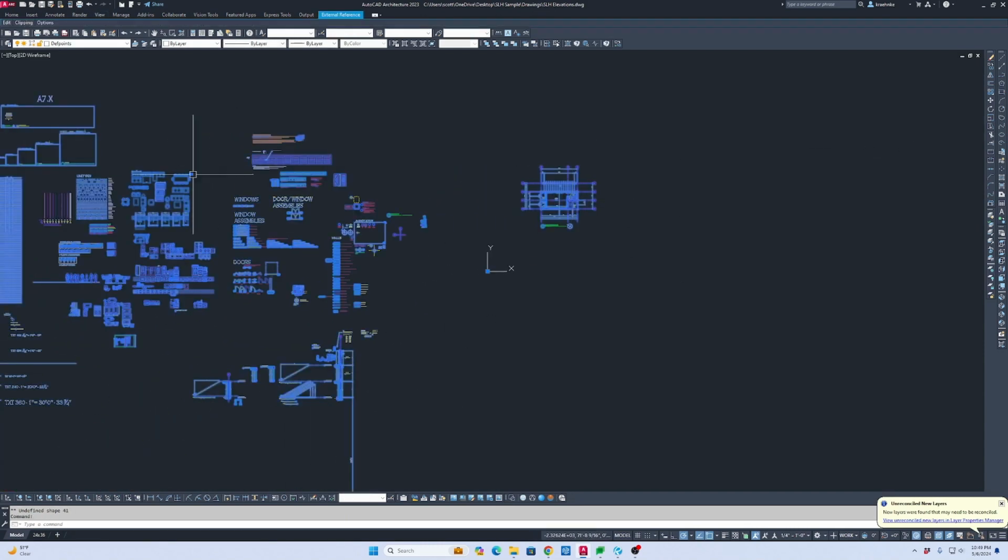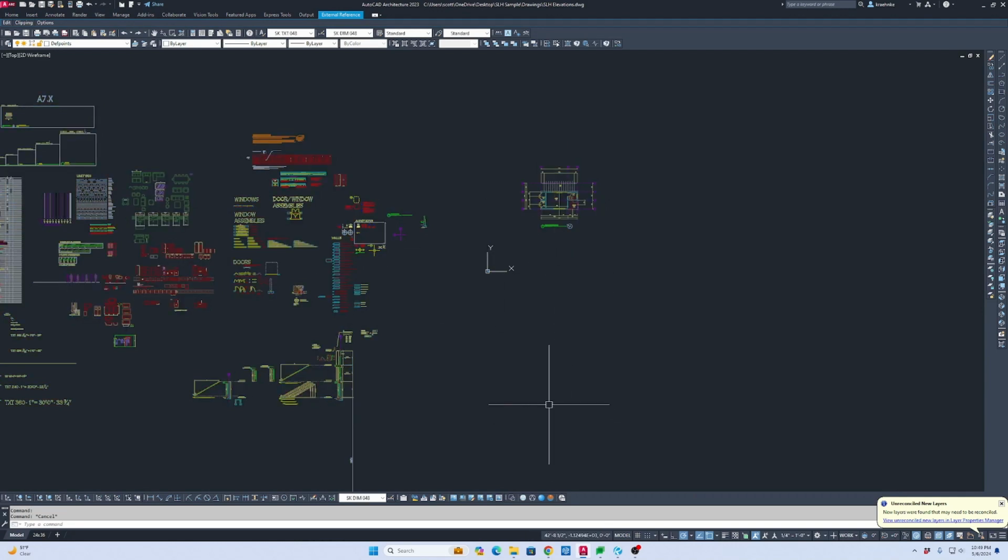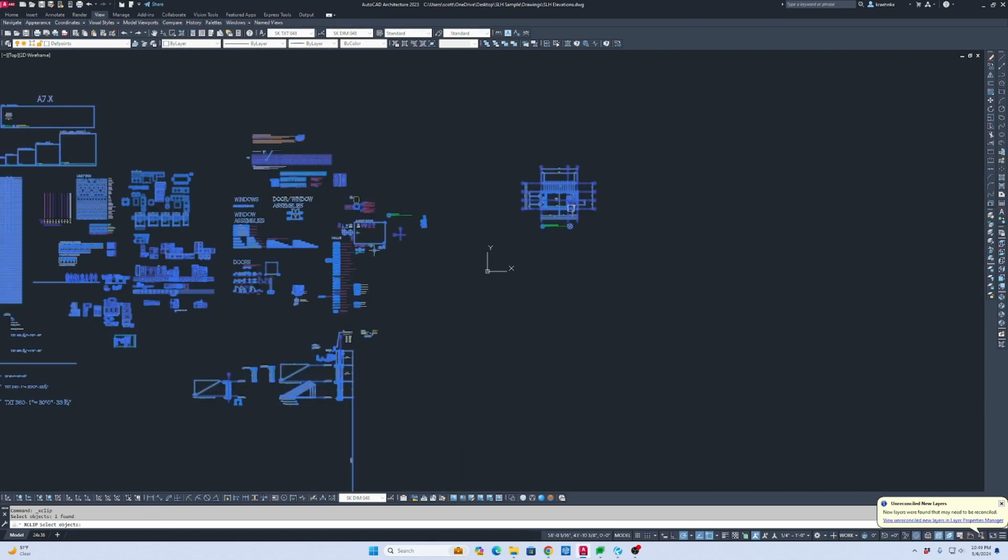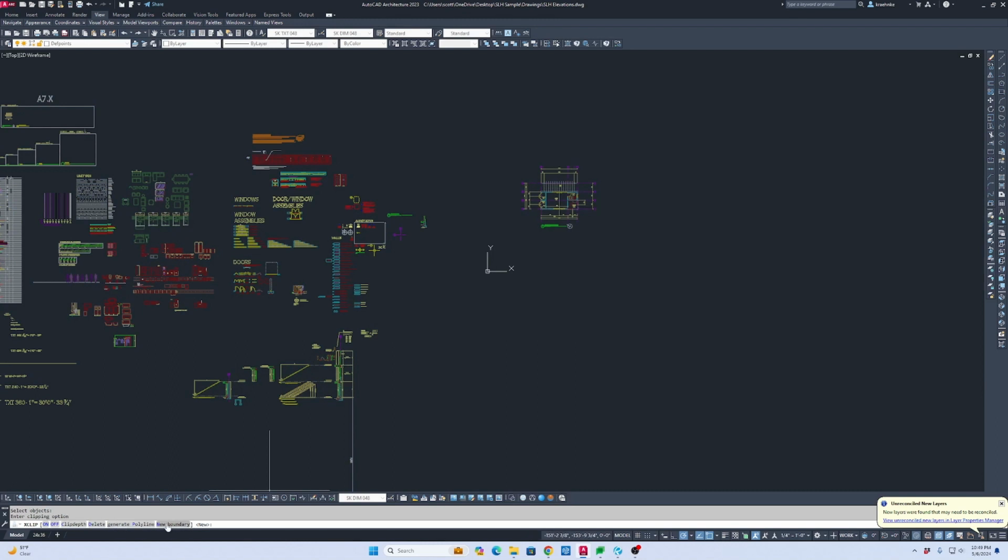And so because that also has a template, we've got a bunch of stuff there. So I normally do an X-clip, which is a command to, actually it's not that, what is the command right here? Yeah, X-clip, I guess I must have just typed it wrong. Where you select the XREF, you can choose a box, a clip, a path.